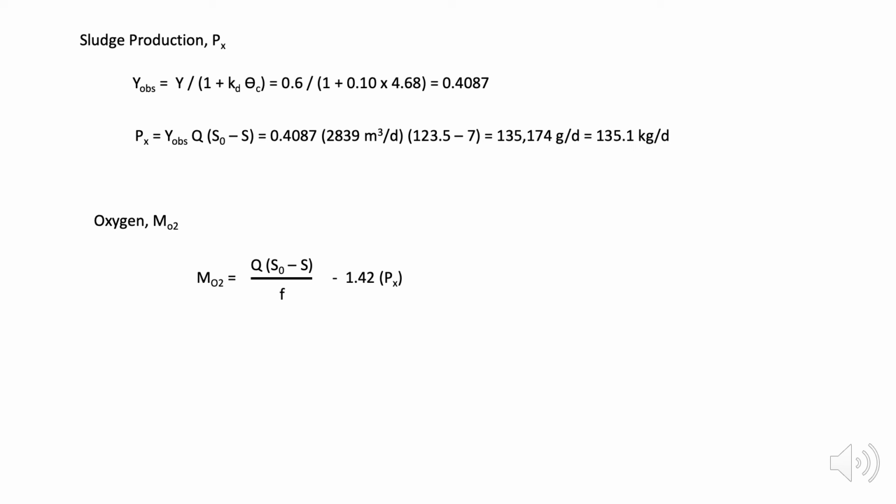If I eliminate cells from the system before they degrade, they haven't exerted a BOD. So if I grow a bunch of cells and then get rid of those cells, they never exerted a BOD, and that lessens the demand for oxygen the system has.